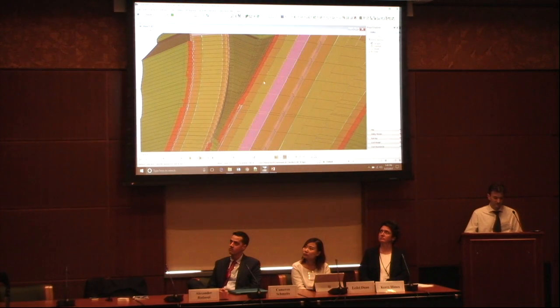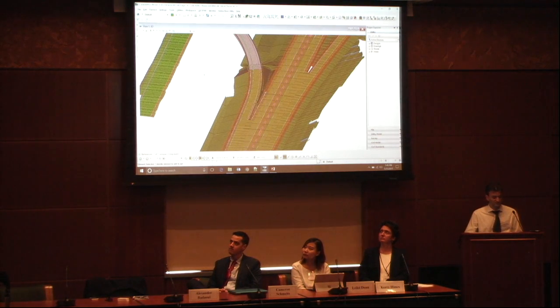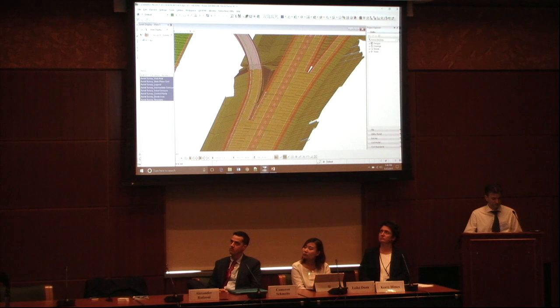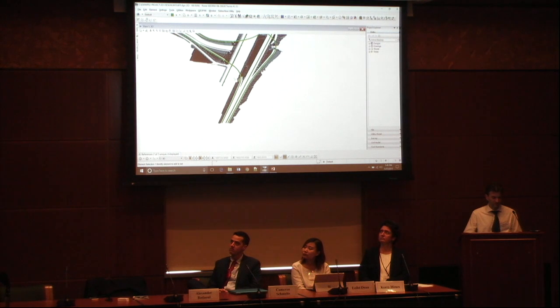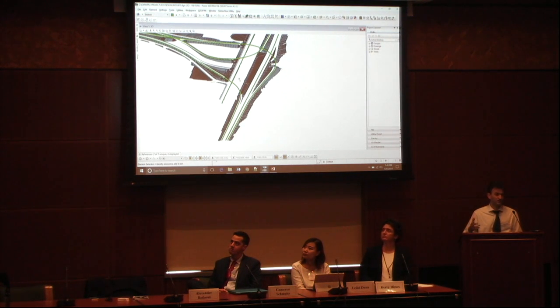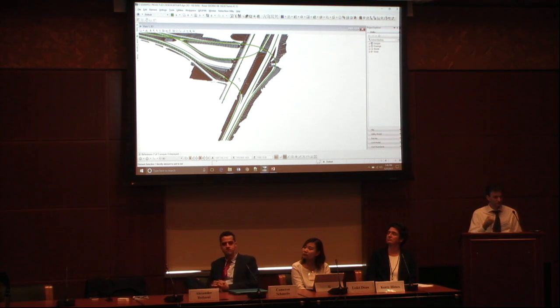Each of these pieces is a unique corridor, so lots of little pieces joined together. Because everything's consistent, I can do level symbology. Turn everything off, and I want to see, that's all my topsoil. One hit quantity, all done, because it all comes from the centralized model. You can't quite do that if you have one piece of template, because you need to ensure that each piece is correct. But while I'm babbling, are there any questions, actually?